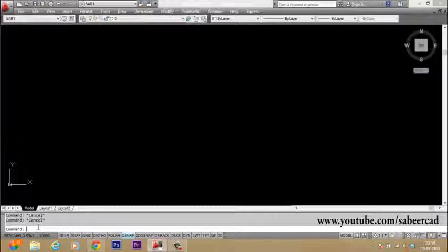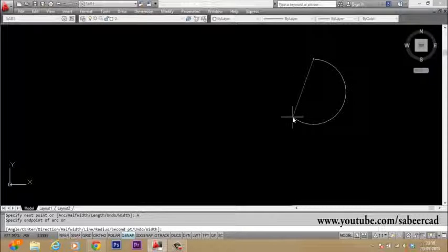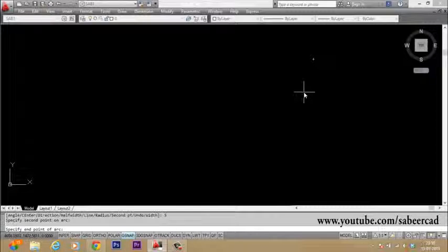How will you make an ice cream cup using AutoCAD? Well, we have to sketch the profile of the cup first using the polyline command. So I give polyline, then I have to start a point from here, then I must go to arc option. Now I should give the second point because I want to change the curvature of the arc.